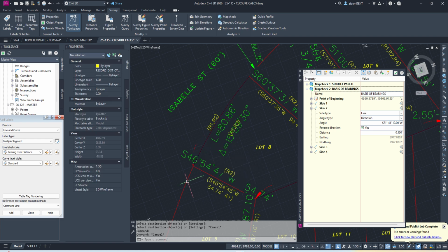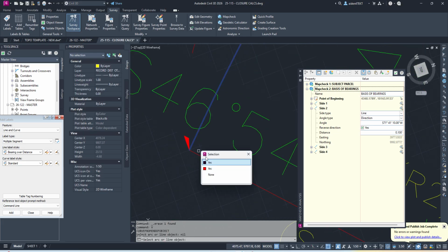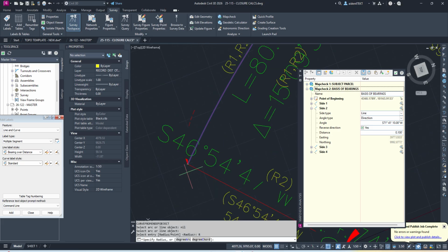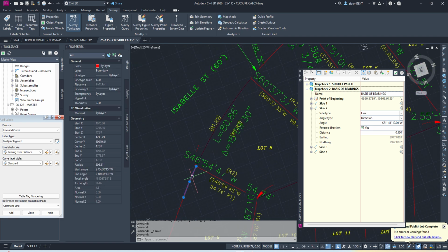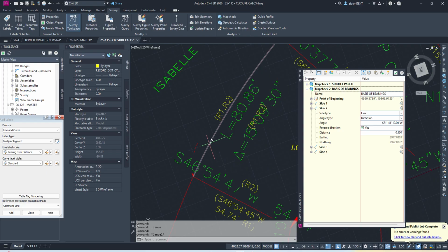307. It's not the same radius. So in that case, you have to go curve end of object. We'll go radius. We're going left, so it's minus 306.31. 306.31 for a length of, looks like 2605. Okay. And 306.31. Yep, that's what the record map is showing too. Okay, so we'll have to do that, or we can copy. I can just copy a base point at this point here.